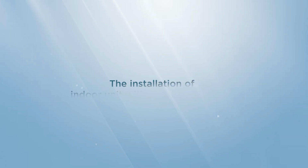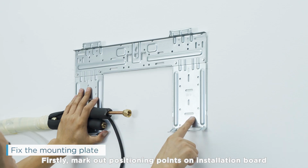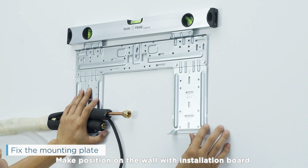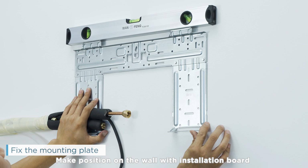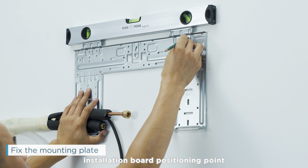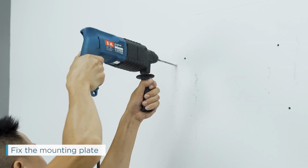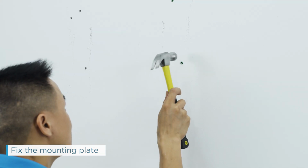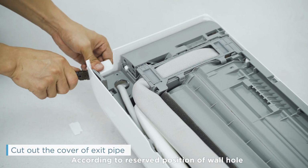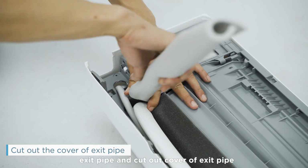The installation of indoor unit with embedded piping. Firstly, mark out positioning points on the installation board according to the length of the input-output pipe. Mark position on the wall with the installation board according to the position of the embedded pipeline and the installation board positioning point. Determine the installation position of the indoor unit. According to the reserved position of the wall hole, confirm the direction of the exit pipe and cut out the cover of the exit pipe.